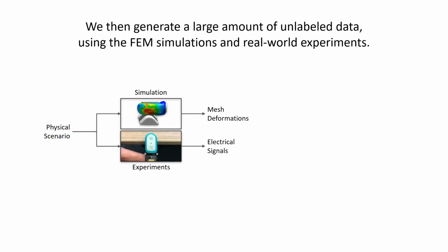With our calibrated and validated simulator in hand, we generated a large amount of finite element data from randomized interactions of the BioTac with 9 additional objects. We also generated electrical data from the BioTac through randomized interactions of the real-world sensor with real-world versions of these objects. These datasets are unlabeled. In other words, we do not know correspondences between the finite element data and the electrical signals.